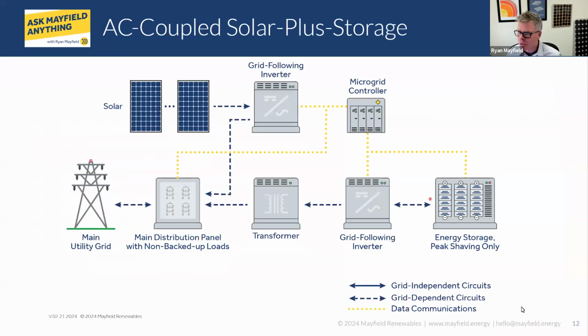So this was a good question that came up. I saw it draw a differentiation between grid following versus grid forming inverters. I think maybe we didn't talk about that in our prep call, so I'm hopefully not throwing everybody off when I bring this up. When we're talking about the energy storage inverter, in this image we're showing a PV system with the grid, a typical grid following inverter, just a grid direct inverter. And then also showing, in some cases, energy storage inverters that are doing the same thing. They're grid following, there for grid services only.